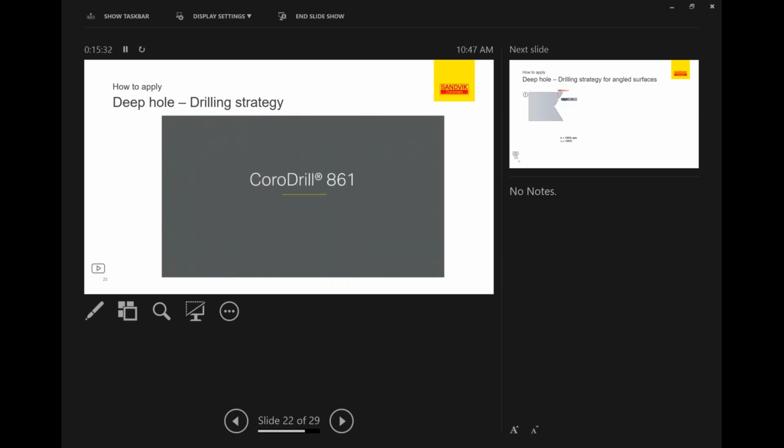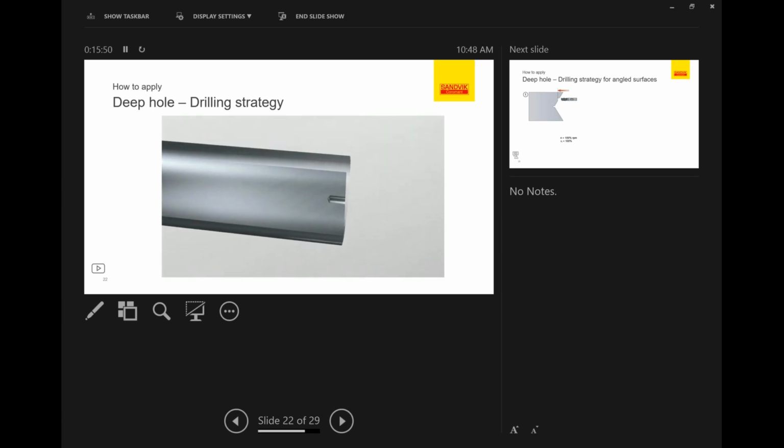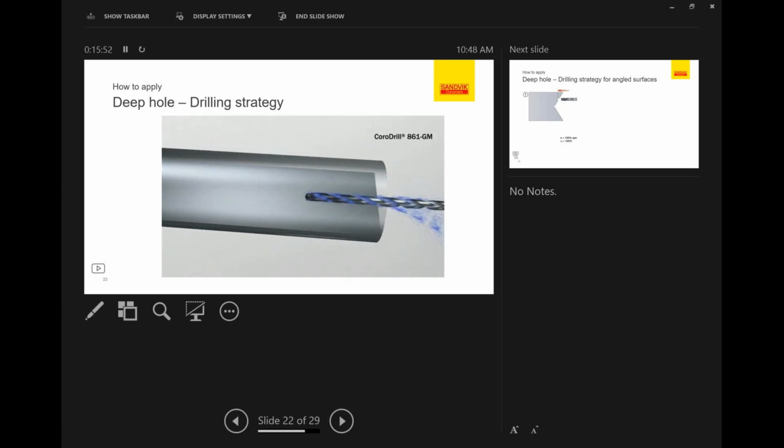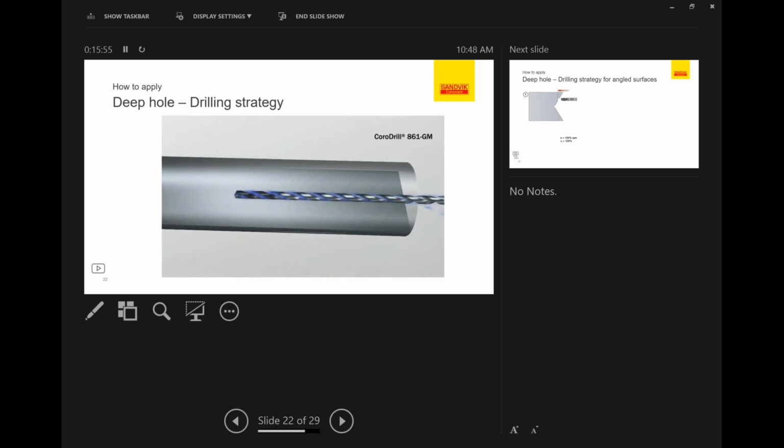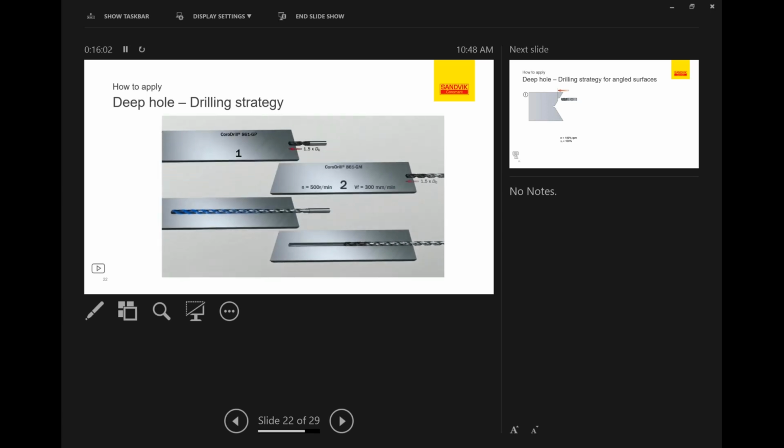Now we'll just show a little video showing the same animation, showing the actual process with the deep hole drilling with the pilot. The deep hole drill has double margins, which again helps guide the tool as you get down and for straightness. So here your pilot's drilled your 1.5, 2 times. The long drill enters, coolant on, feed and speed up to 100%, drill to depth, retract, slow rate, and now that's completed the cycle. So if we follow the strategy, usually it does a very good job.